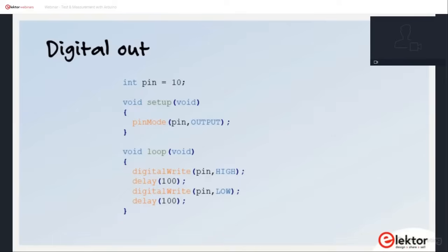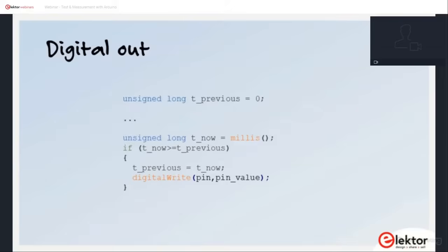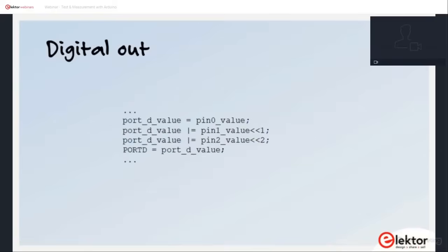You can use the Arduino function digitalWrite in a loop to generate square waves or more complex signals, or very slow signals on one or more pins. To get a stable frequency, the loop must be timed by using, for instance, the function millis, and any interrupts that are running should be processed as quickly as possible. Like digitalRead, digitalWrite can only do one pin at a time.